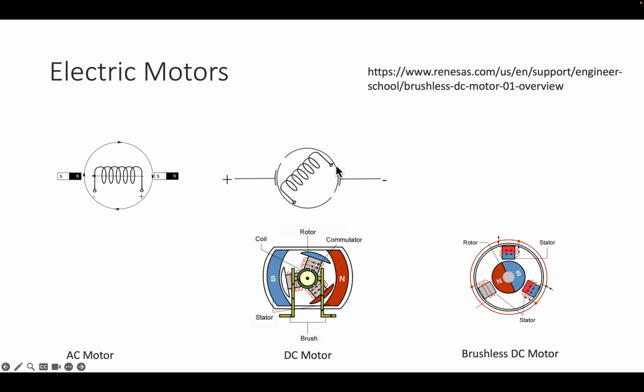And as the thing turns, this piece of the rotor will hit the brush here, and then the right side of the coil will be powered. Now, if I have AC current, alternating current, I can power a motor like this directly. If I have DC current, like voltage that doesn't change, like out of a battery, I will need this commutator framework.